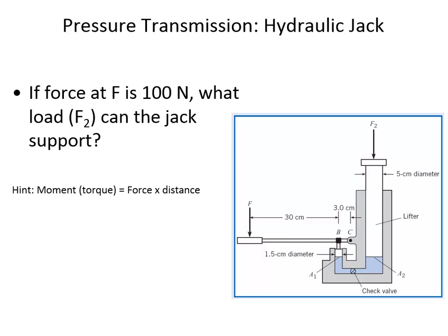It's going to be a very small pressure change. And so it probably wouldn't even be measurable even if it was a meter elevation difference. But in this example, since they're by inspection, we can tell that they're at the same elevation. We don't even have to worry about the difference in pressure acting on one versus acting on two.